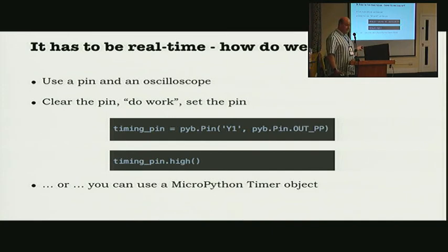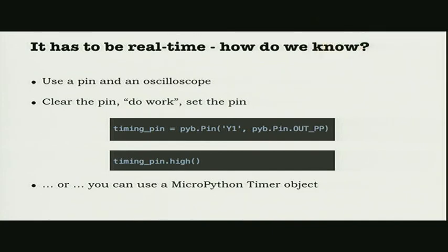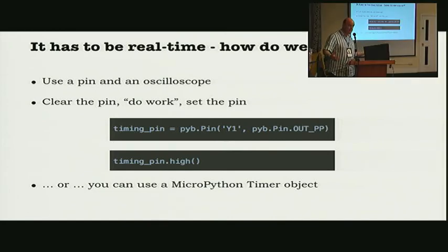In this particular application, everything has to be real time. I've got no control over how long I want to sit around and take samples. I have to take them once every 1/8,000th of a second. If I don't, the audio playback is going to be corrupted. It's just going to sound awful. So you have to have some mechanism that allows you to record data. The other thing is that you were doing some audio processing, so we're capturing samples and putting them on the board in memory. We have to be sure that we aren't going to breach that 1/8,000th of a second.